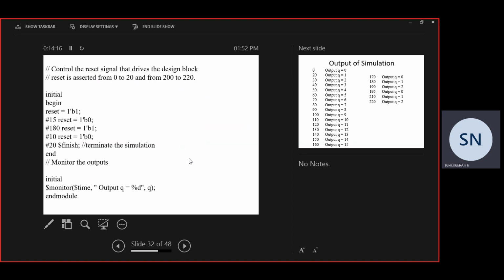Now for the next clock signal, it will be 0 0 1, the same, because a 0 to 1 transition is not going to affect this output. Correct? Whenever this goes from 1 to 0, in the next case it is 0 0 1 0 0. So here, when there is a 1 to 0 transition, it will go to 0, and that 1 to 0 transition will act as a clock for the third. So you are getting this as the output.